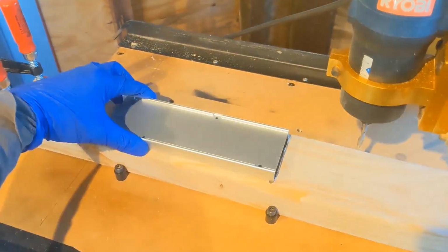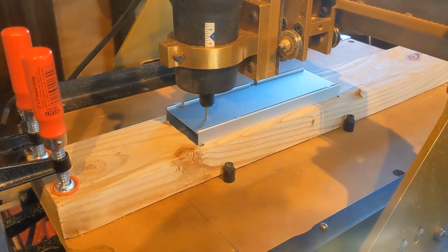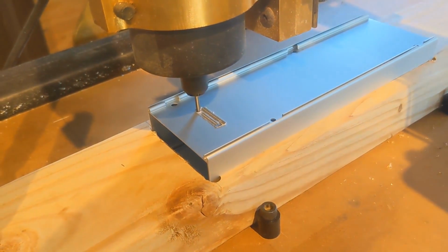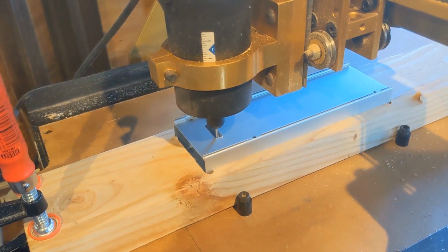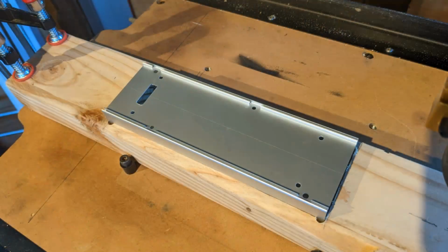It's a very tight fit. Might be a little tough to remove. The first cut is a rounded rectangle to allow the wiring header on the back of the OLED to pass through into the enclosure. Next, 4 holes are cut for the display mounting holes. Here's the final results cut with CNC accuracy.